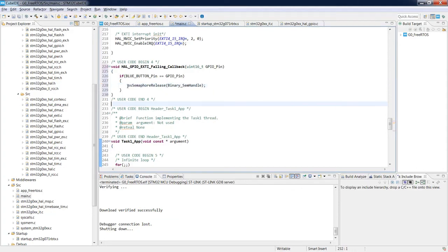One more thing on this point. Executing code within this callback is still done within the interrupt routine of the external interrupt from line 13. This is an important point because please remember that our hardware interrupts should not interfere with the operating system. The cooperation between hardware interrupts and operating system functions should be done in a careful way. The big advantage of this CMSIS layer is that the CMSIS library takes care of selecting the proper function, whether we are calling the operating system function from the normal code or from the interrupt routines.